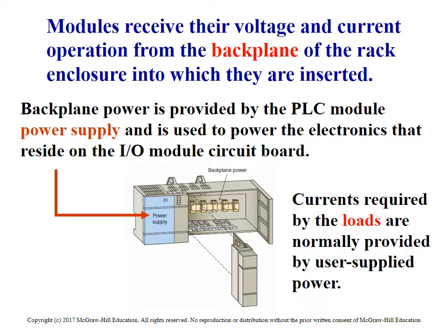All the cards receive their power from the power supply. As you can see here on the left, that power supply feeds all the cards using this backplane. That's pretty typical even with all the new equipment. The one thing that is different in the newer equipment is that you can put the power supply in more than one slot. It doesn't necessarily have to sit to the left anymore. It can sit anywhere on this bus bar, and you can have more than one power supply if you need more power.